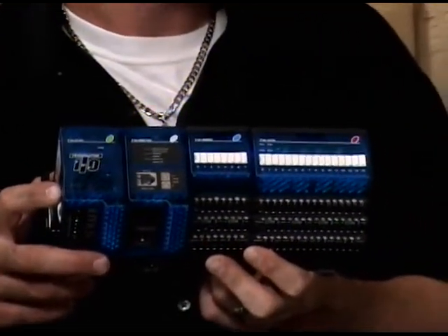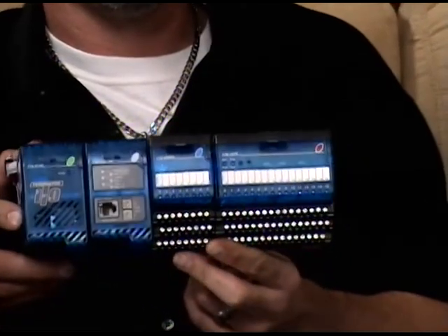The one thing I think is really nice is I can be sitting here with a DL205 with, let's say, a 260 CPU with an ERM, right? Correct. And I can talk out to a remote base with an EBC module in it through a hub or a switch, right? Probably a switch. But in this case, it's a remote D2 type I/O rack. But I can also use the Terminator, which Shane is holding over here. So I can use field I/O, which is nice because I can stack that up all over the place and actually hang that out there and be talking the 260 CPU out to it.